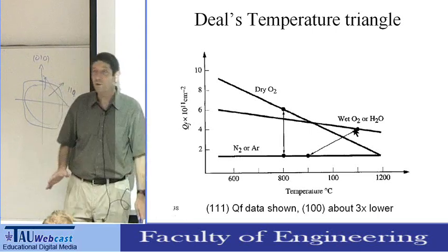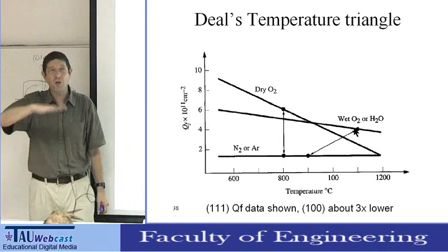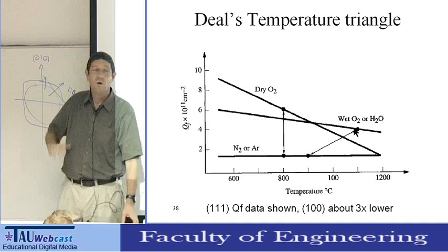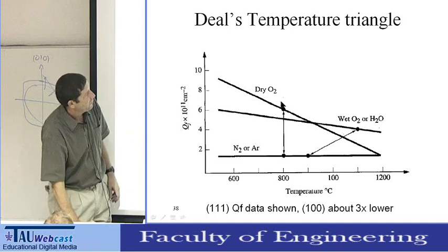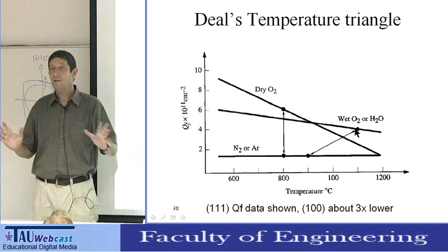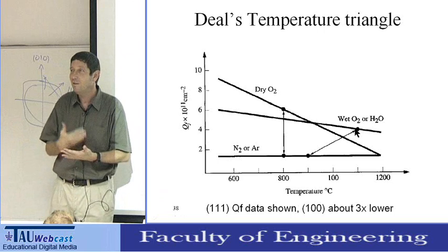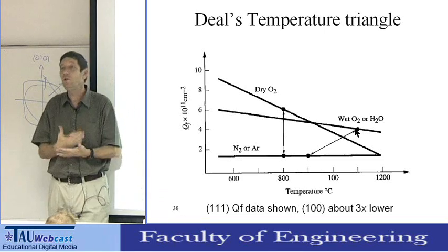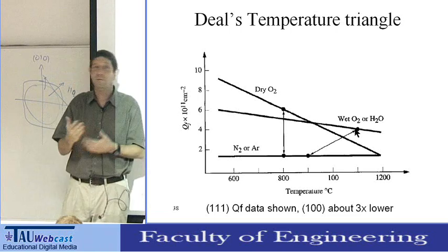So it was discovered that if I want to have a low charge density, I need to anneal in nitrogen or in dry oxygen, but not in steam. It's an experimental fact.